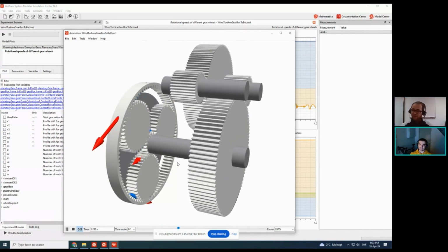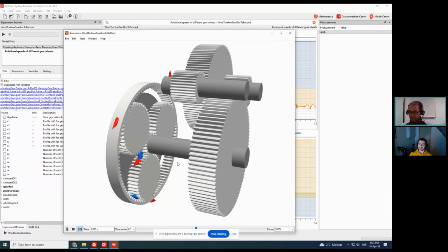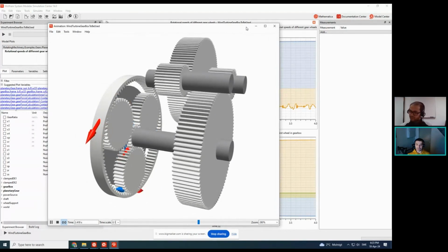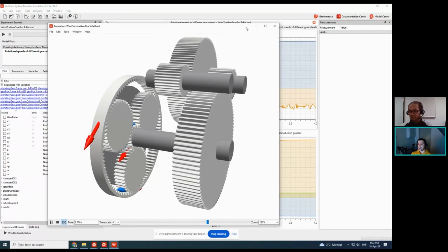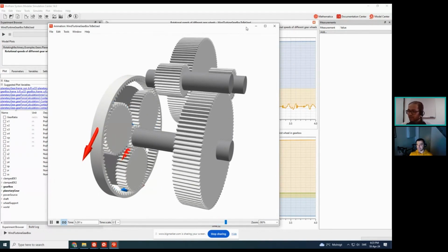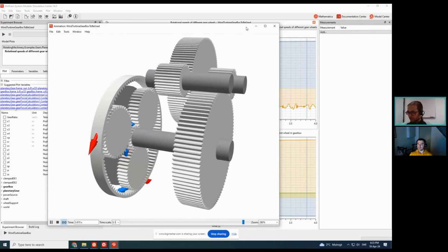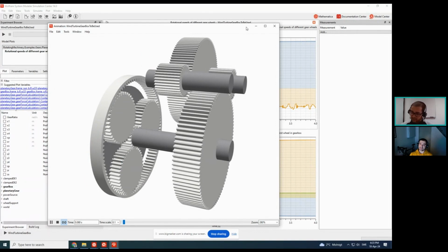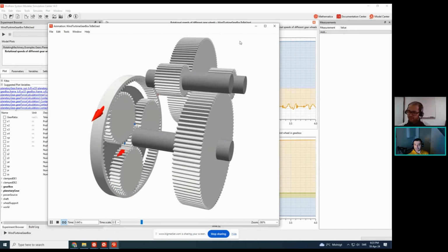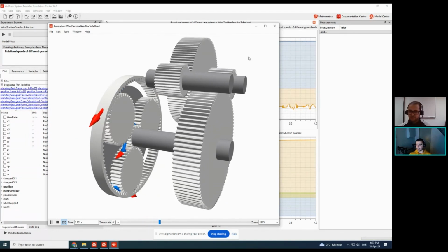Yes. So the objective of this model is to model the contact forces and the effect of those contact forces on the gear teeth. We want to understand if those stresses are within the design limit, else it will lead to gear tooth failures, and to understand the cyclic stresses. And all these components we see, the shafts, are all flexible, so flexibility-related dynamics are also taken care of.